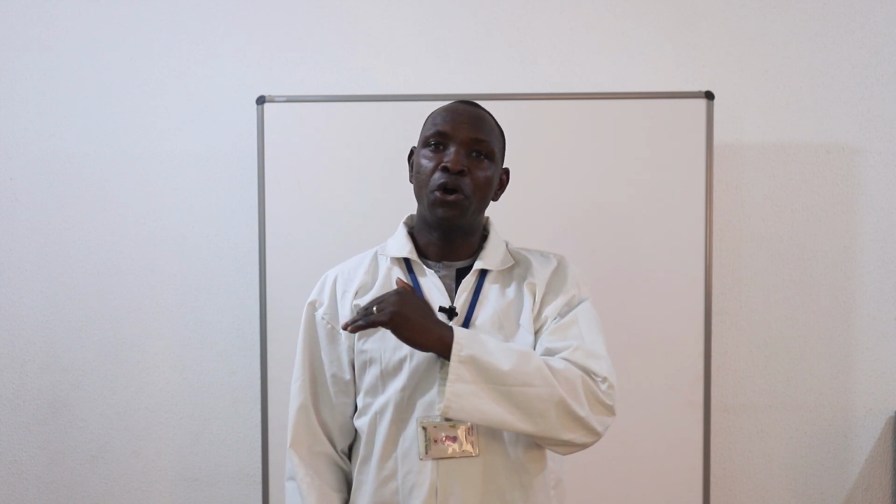That is, the bubble between the length of the spirit level must be central to confirm that the work or the surface is perfectly vertical or perfectly horizontal, as the case may be. Therefore, this spirit level must be placed on a true surface while using it. That is, the air bubble in the vial of the level must stay in the center, as I earlier mentioned. There are different types of spirit level ranging from 900 mm to 2000 mm in length.